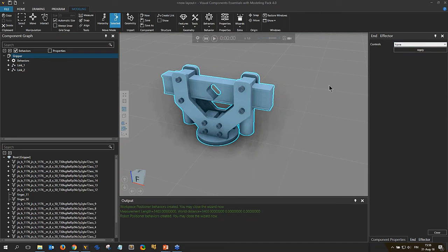But in this case, when we have a mechanical gripper, we want to control that. We can control that joint either as an external axis. If it would be some super nice servo control joint, we would probably use that. But if it's some sort of pneumatic axis that it can open and close, I will probably go with the I/O. So I can fire true to close, false to open. I choose controls I/O, I hit apply and close this.